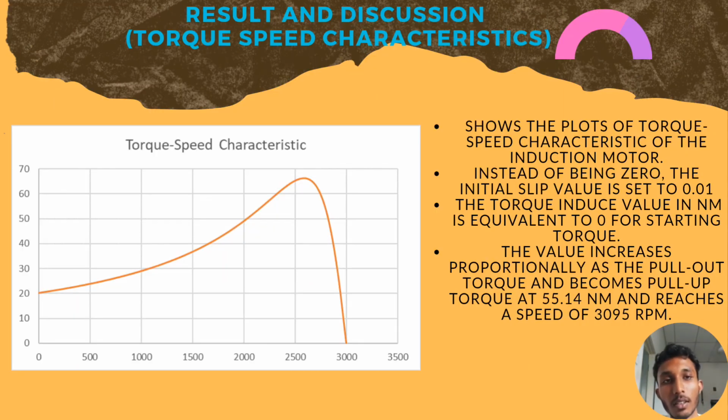We can summarize that the torque-speed characteristic graph represents how torque varies with speed, whereas speed is on the horizontal axis and torque on the vertical axis. As we can see, the shape of the curve varies depending on the motor design, load conditions, and applied voltage. The graph typically shows a curve where torque decreases with increasing speed. This is because as the motor speeds up, the back EMF induced in the motor winding increases, which opposes the applied voltage and reduces the effective torque output.